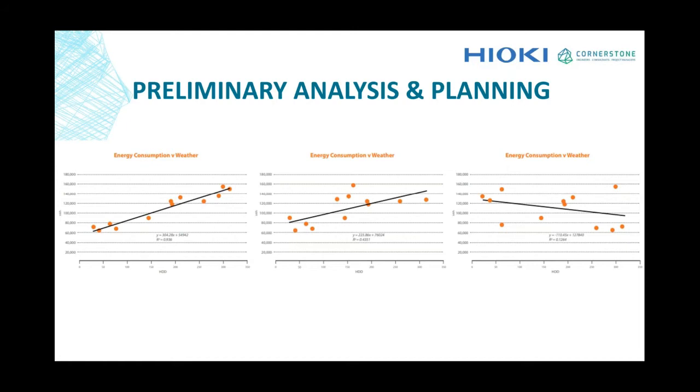Basically, we are able to do a statistical model and predict to see how the model fits the drive of the variables. For example, you will see that weather and occupancy are a major driver here for a mixed-use building. So maybe a combination of that gives you an understanding of where the building energy consumption is driven by.